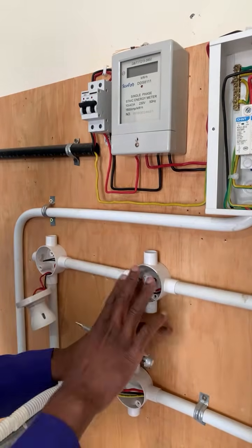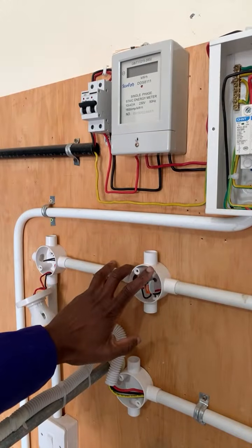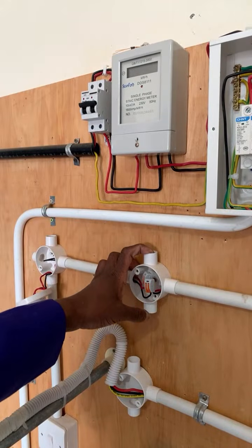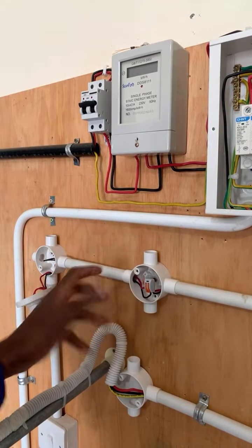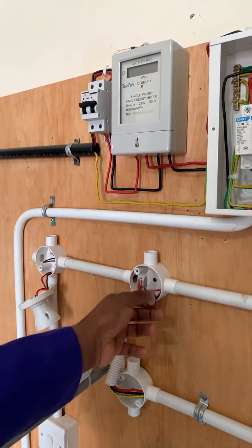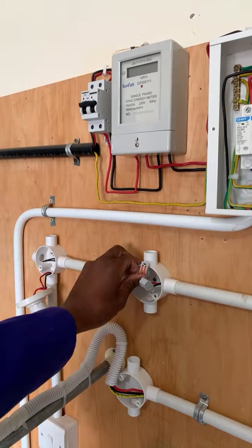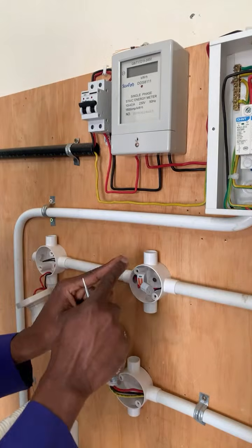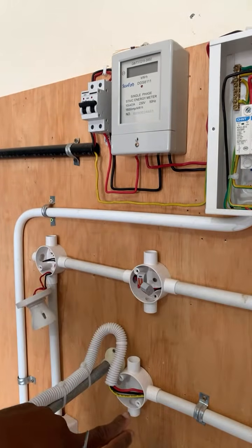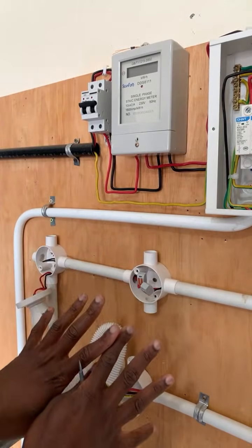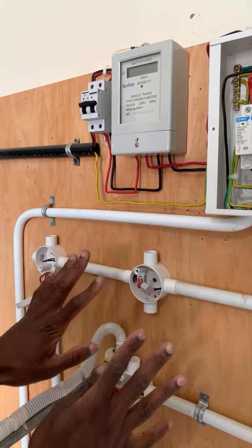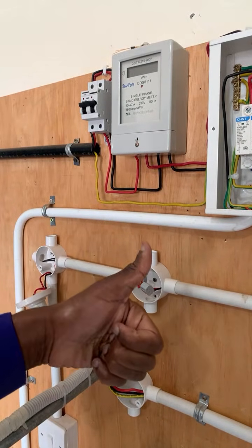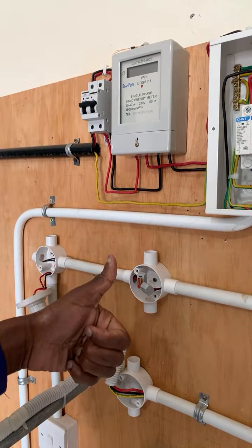So, in this lighting setup, my top bosses, as the name suggests, it is light. Probably taken literally, it is lighter. So the size of the cable is smaller. This is a 1.5 mm cable. Now, if someone decides to use a 1.5 for socket installation, and they are very comfortable about it, what are the hazards that we must foresee coming? Someone decides, you know what, I want to use a 1.5 cable for socket wiring.